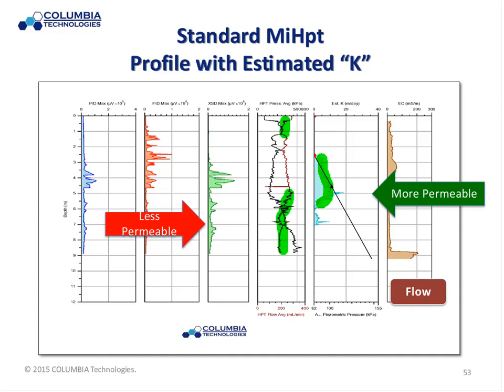Come over here and look at our detectors. We've got a PID response. We've got some FID, what I call smear here, and we're looking at XSD response. So what we really have here is a chlorinated site. Most likely this is a methane off gas, but this is an example of that migration or transport zone that's going on, where we've got permeability here and contaminant, as opposed to the storage zone I showed you earlier. Swapped compounds on you, but the point is the same.